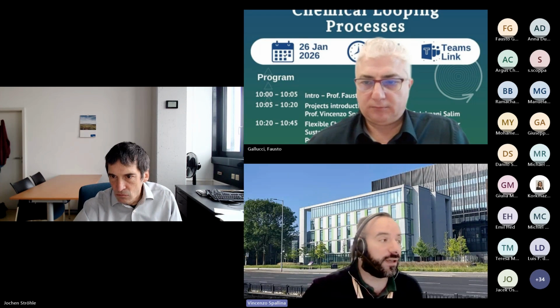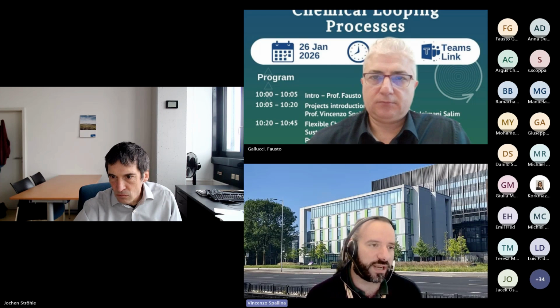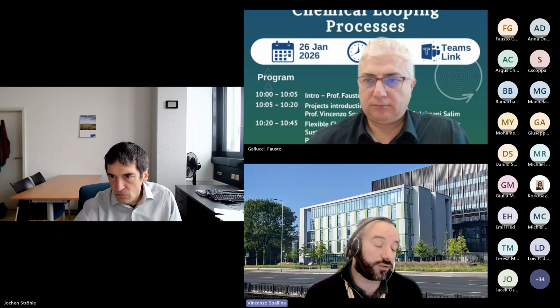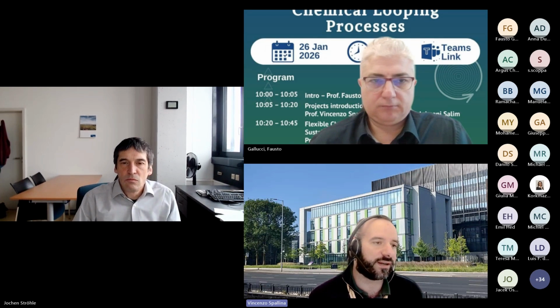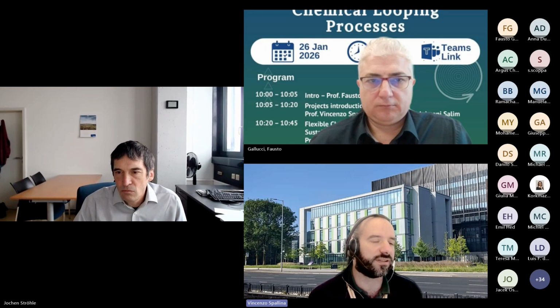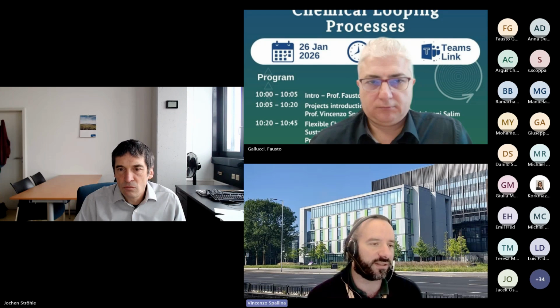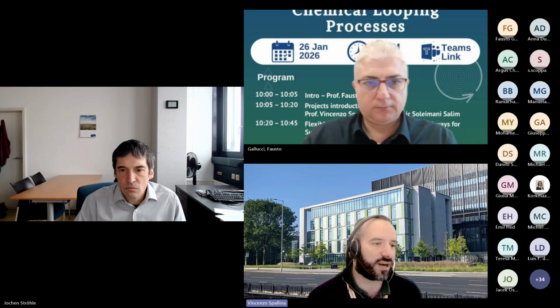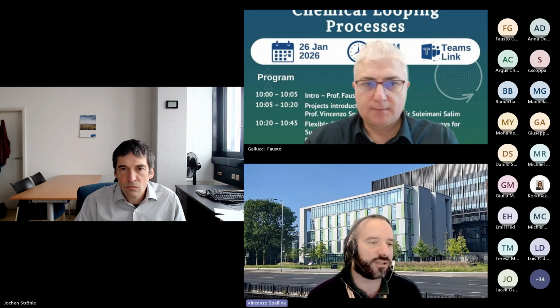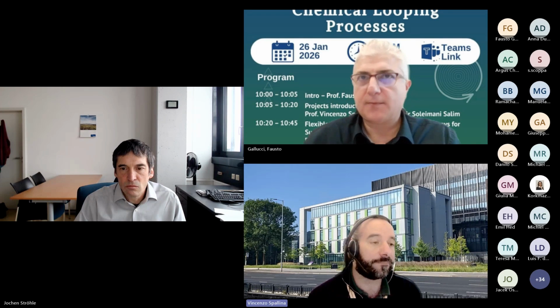So the question was about the availability of, and the supply chain for, packed bed reactors. The reason why I think this is more complex at the moment is because the system is new. It operates under short switching times, so valves and materials for reactor piping need to be designed to withstand this chemical and thermal stress. The temperature during the oxidation rises by 400 degrees Celsius, then drops and rises again. So these are challenges which need to be addressed.